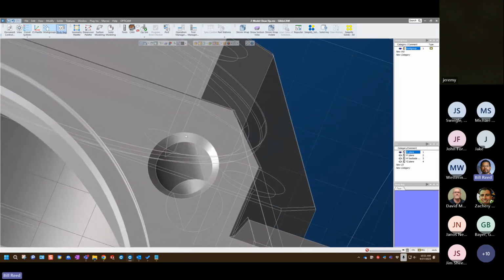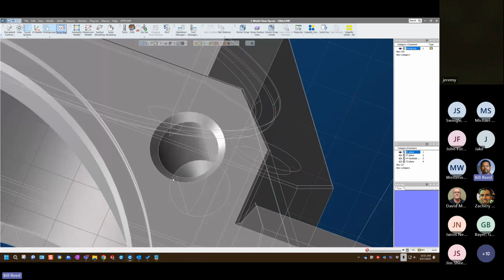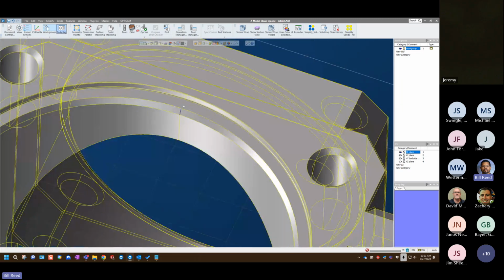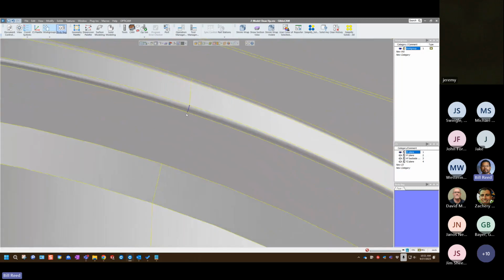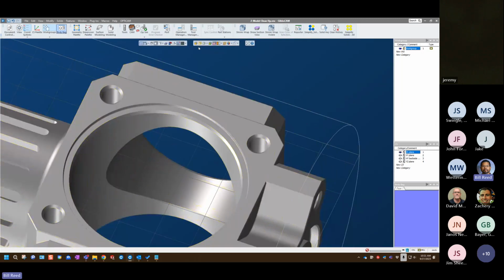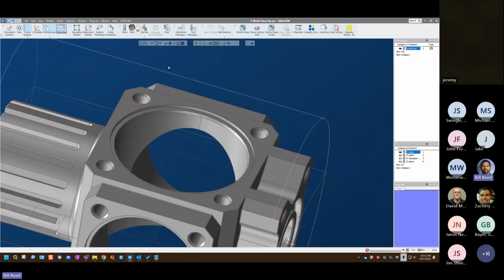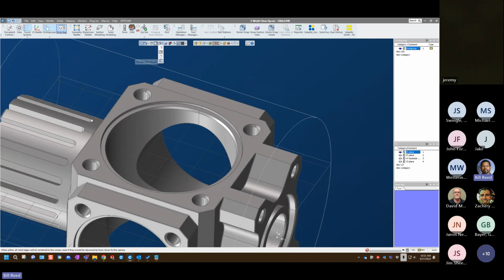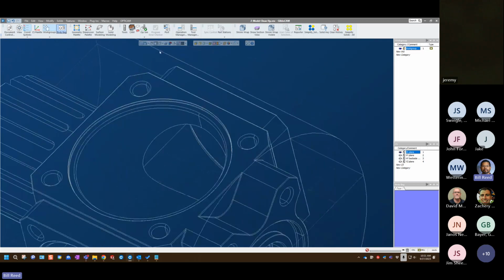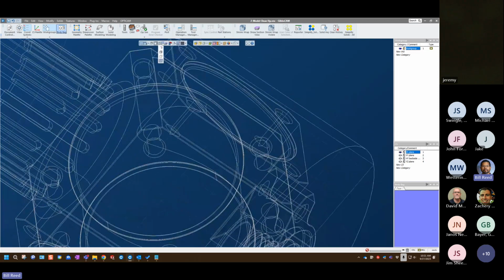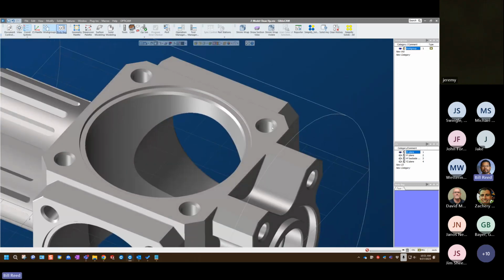And if I turn on edge selection, edge selection will show you all of the intersections between all the facets or faces of your model. And I can see that my countersink and my ID and my drill tip all have breaks in it, as well as my large diameter bore countersinks there, and including the small radii. Now, another way you can see these without using face selection is controlling the visibility of the model itself. So I have render solid faces. I have this, which will highlight all the vertices. Sometimes I want to use this mode. And lesser used modes are this one here, which kind of shows you a wireframe, and this one will show you transparent faces. So all of these methods will show you those breaks that are in some of our cylinders.